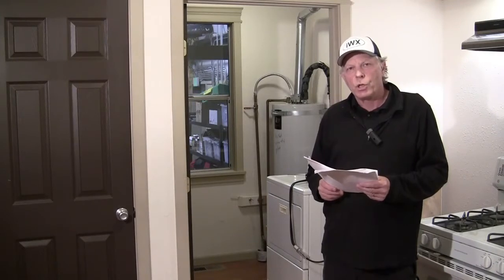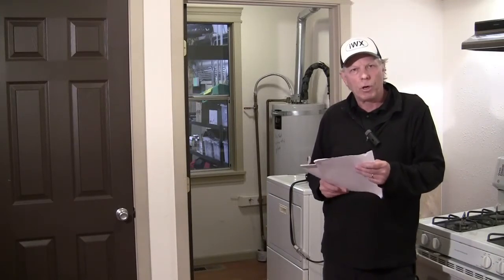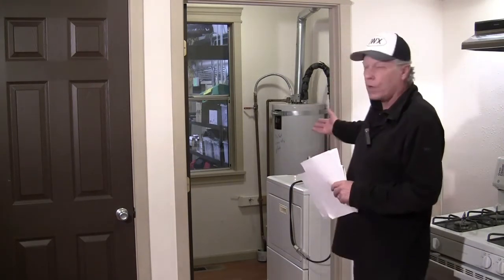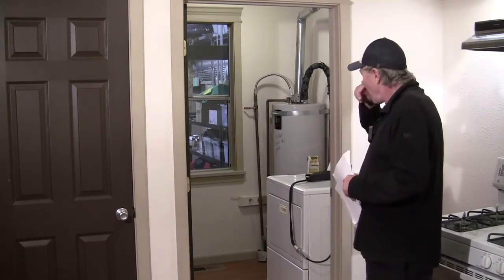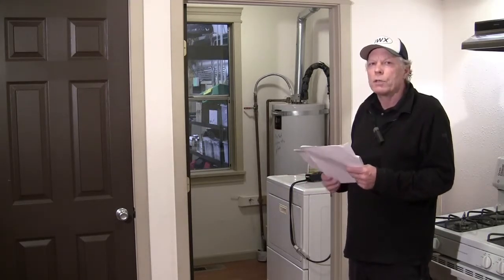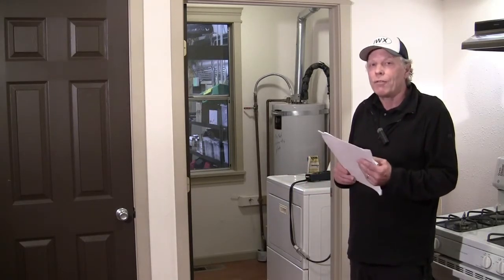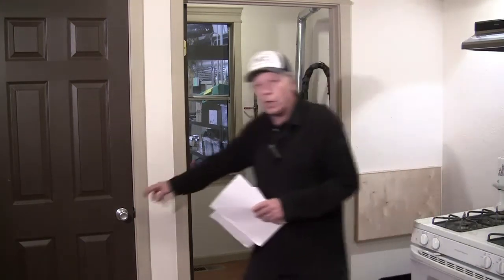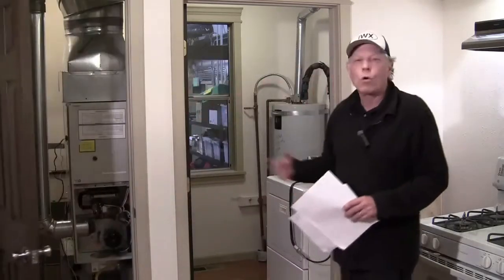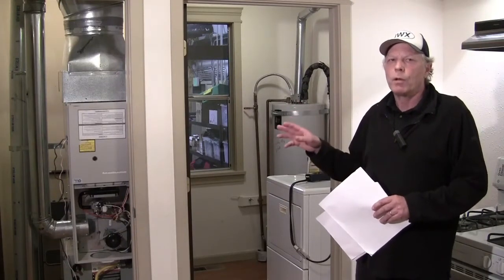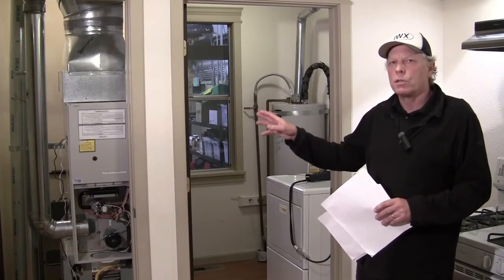Okay, we're on our combustion appliance zone testing portion of the Energy Auditor field guide, and we're going to start with line number 1. We're going to be using this combustion appliance zone here. It's a standalone natural draft water heater. So it is a category 1 chimney with a draft hood, so it's one that we will test for spillage. All right. In this closet here, we have a category 1 80% efficient furnace. It does not have a draft hood or barometric damper, so we're not going to be testing this for spillage.